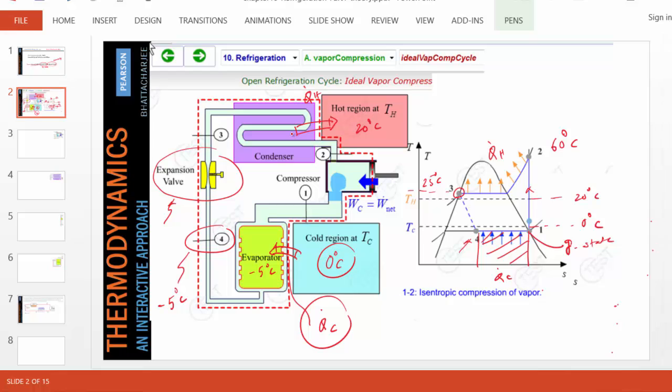So at the end of the condenser, the fluid after it condenses comes out as a saturated liquid at state 3, and there it expands in the expansion valve where enthalpy remains constant, we will find. And as a result, the constant enthalpy line in a TS diagram looks somewhat like this. Entropy is increasing while temperature drops, and we complete the cycle. Okay, let's go device by device, and then the picture will be clearer.